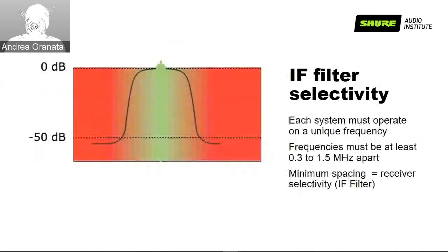And luckily, it's not like audio, where we can be over selective and have very efficient brick wall filters up to, I don't know, 48 or even 100 dB per octave. Here, things are working slightly different. The shape of a filter, as you can see from the picture, is not a brick wall at all, and this has an effect on how we work with it and how filters are built.